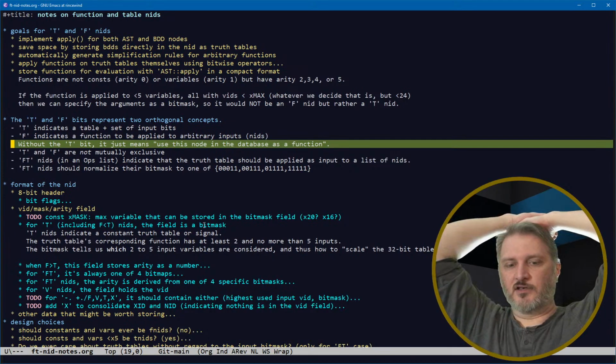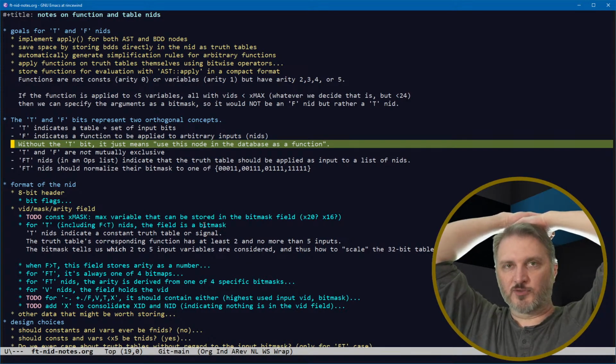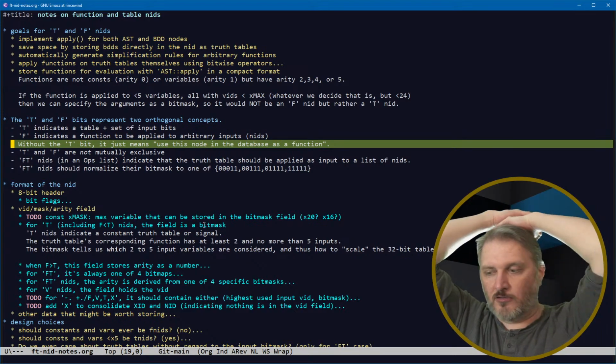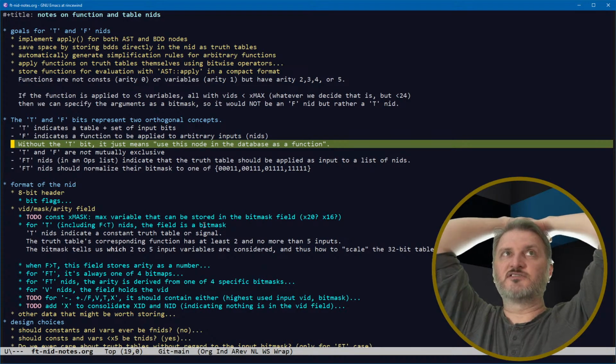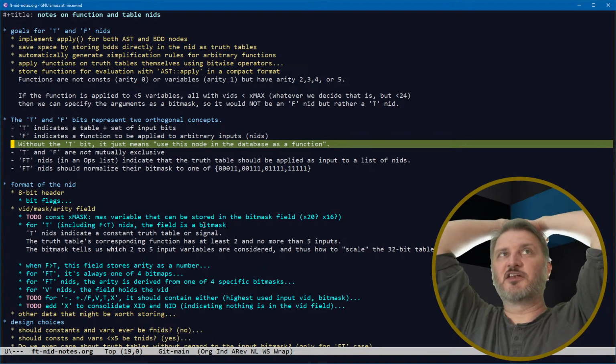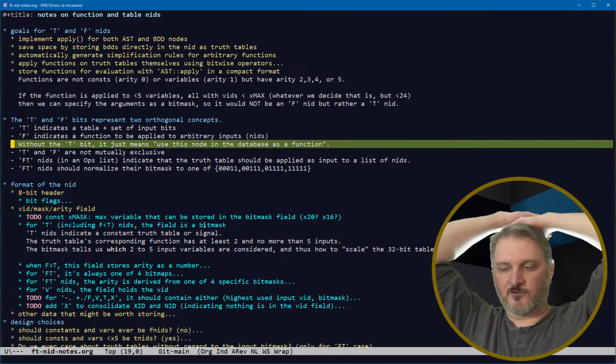And so you've got 32 separate functions that only deal with the results of the carries, right? But those results depend on all 64 input bits. So there are 33 functions that depend on 64 bits, one that depends on 62 bits, one that depends on 60 bits, and so on and so on and so forth.